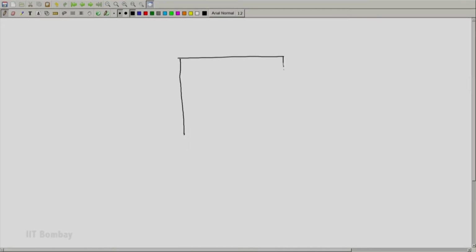So, here I did not need to worry about taking any impulse response and going through the impulse response. I could directly use my elementary knowledge of electric circuits. And in fact, the beauty is, since this system is linear, I can take each of these components in turn, analyze what happens as a consequence of applying that component to the system, and then superpose. The principle of superposition holds. So, now we can write down the output to the entire periodic input x(t). That is very simple to do.